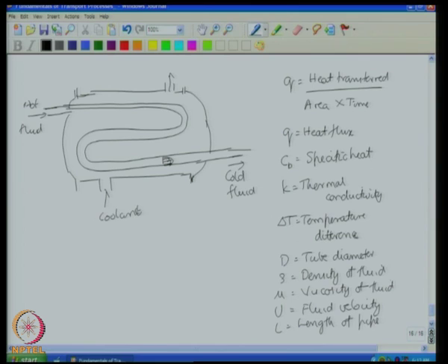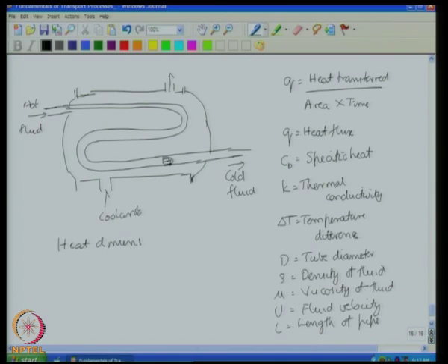So here the assumption is that the heat flux is an energy per unit area per unit time. However, if there is no conversion of heat energy into mechanical energy, then the heat energy can be considered as a dimension all by itself. There is no conversion between heat and mechanical energy. So, the heat energy has to be conserved. So, rather than consider heat and mechanical energy as equivalent things, we can consider them as different things, and assign a different dimension, heat dimension, with the symbol H.